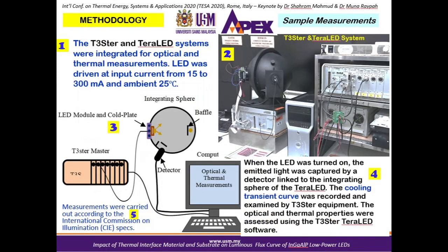In our lab, we have T-tester and parallel system as shown in the photograph of item 2. We use this system to measure the optical and thermal properties of the LED packages. Item 3 shows the schematic diagram of the measuring system. The location of the mounting of the LED package is shown there.